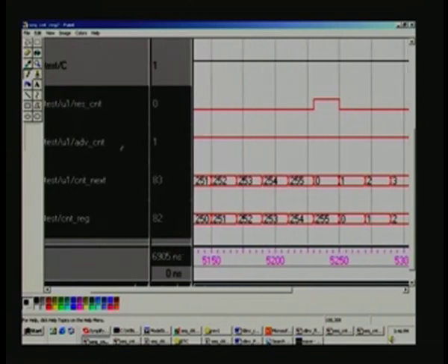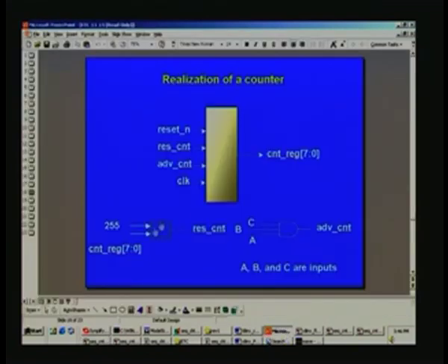Here you see this advance count, but in the optimized one you are unable to see it because it has been removed, although the actual signal itself is not removed; it may be preserved under some other name. So right at 255 it gives one reset output. That is what we have for resetting, is it not? As per this, it should reset when the two match.